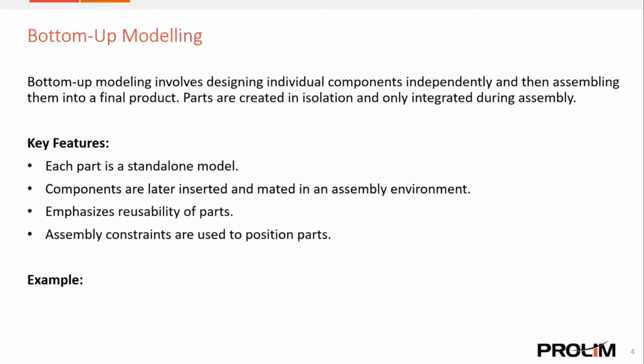Also, assembly constraints are used to position those parts, usually with top-down. Some people use a model driving off of another model to keep those two constrained together. That's not our recommended approach. I would still recommend using your assembly constraints to position them appropriately, because if you change one piece of the model or something in a subassembly, things might move to where you can't get to them, or completely out of the model or where you need them to be.